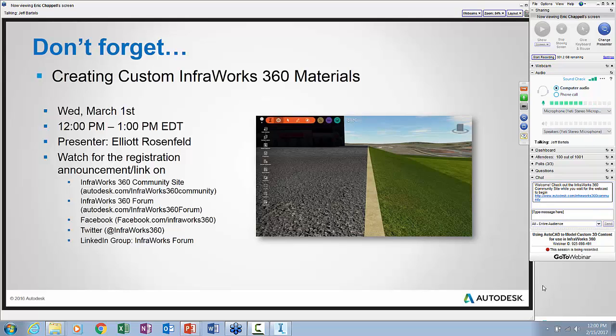I used feature lines to define my curb and gutter, and feature lines to define the sidewalks and all of the proposed break lines, if you will. That's how I modeled the site, and then I created a surface out of that in Civil 3D, exported that surface via land.xml, and then brought that into InfraWorks. And then I also took the shapes that I used in Civil 3D that represent the back curb and the islands and things like that, and I exported those as shape files that I could drop into InfraWorks as coverages to essentially paint materials over the top of that land.xml surface.